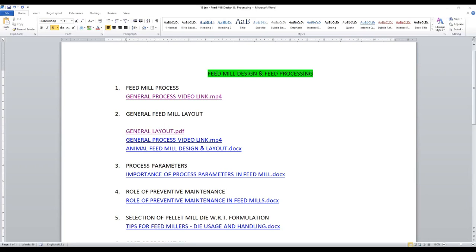But now we have to calculate the width and the length. We got the complete 42,000 square feet of the warehouse, but what will be the length and the width? In general practice, with respect to the prefab cost and the cost of the warehouse, 80, 90 and 100 feet is the ideal width with respect to cost and installation. After 100 feet, we have to put extra supports in the truss of the feed mill warehouse, and we may also have to add a center column for support. So looking at the cost of the prefab warehouse, 80, 90 and 100 feet is the ideal width.